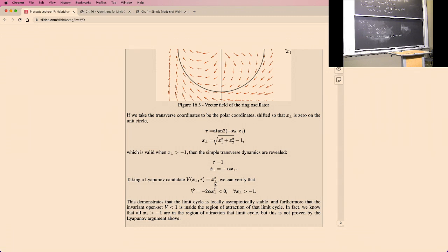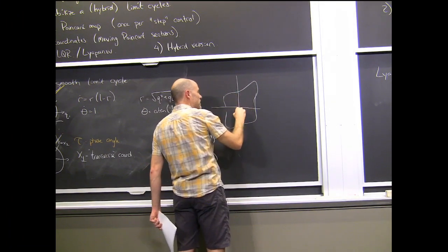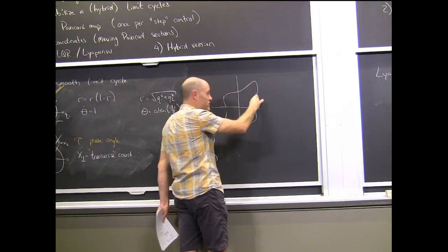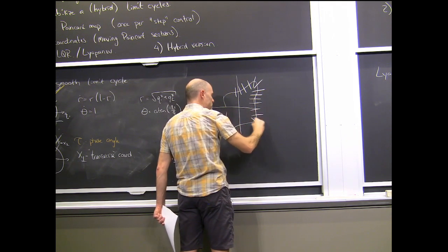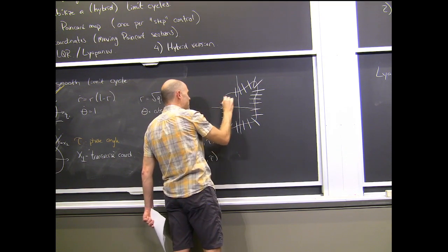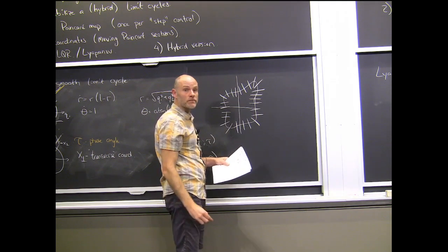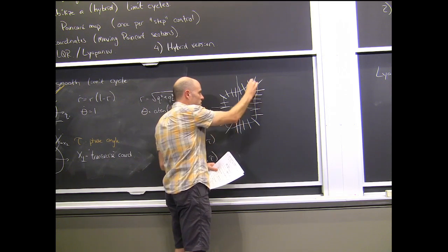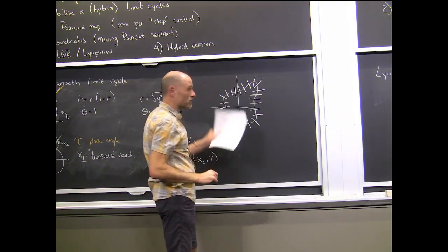Yes? Is this approach restricted if the shape of your cycle is kind of wavy or blobby? Oh, good question. What would you do in that case? Okay, so we definitely have seen a more curvy van der Pol oscillator, right? You could choose things that go directly out from the origin and maybe be okay, but you could find systems where that might be hard. What we tend to do is potentially solve an optimization problem to find nice, smooth surfaces of section that move along. And it's not hard to find ones that are consistent, okay? But finding the one that will give you the biggest region of attraction can be a hard question. Oftentimes it is better to locally try to find a good transverse coordinate rather than just picking a global one, because of the curviness of the trajectories. That's a good question.